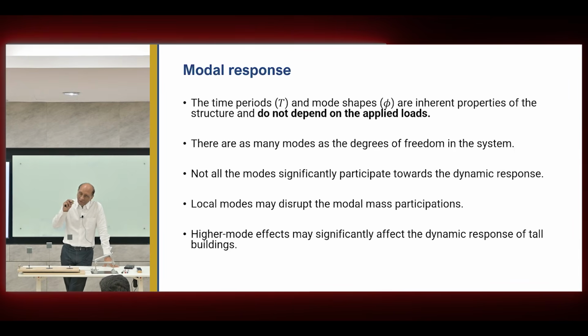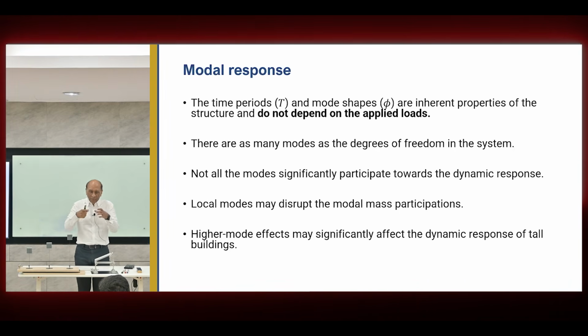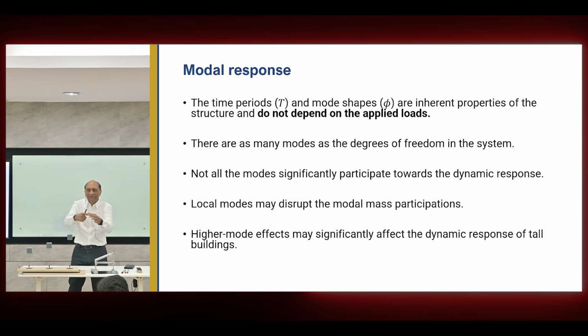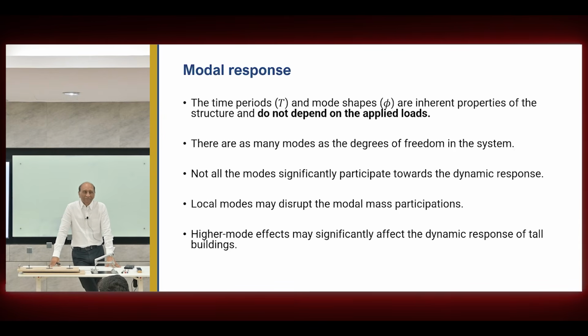7 degrees of freedom is for one particular node or a point of deformation. I'm talking about the whole building. Yes, 7 degrees of freedom if every degree of freedom is free to move independently. But for a building, normally all the columns are connected by the slab, so they will move together. Each column cannot move away. They're going to move together. So this is 1 degree of freedom per floor for X direction, 1 degree of freedom in Y direction, and the whole thing is rotating, just like I broke this one, exactly like that, right?